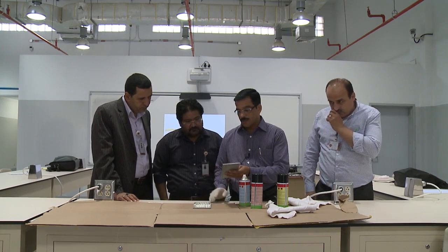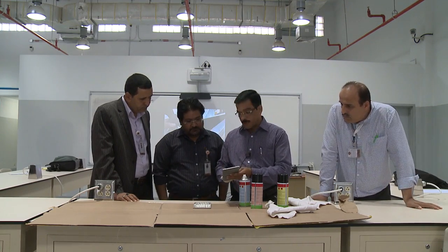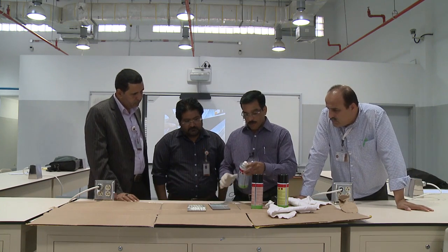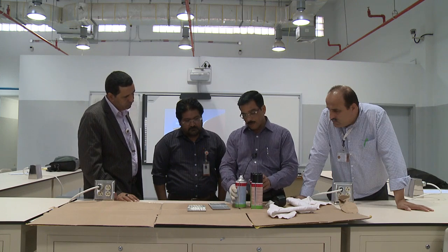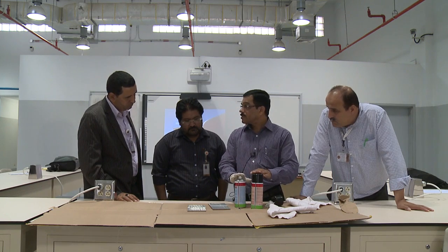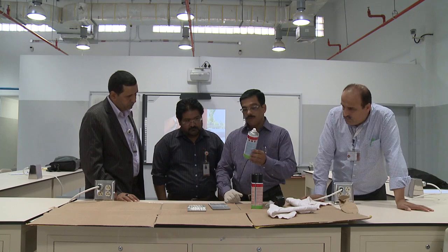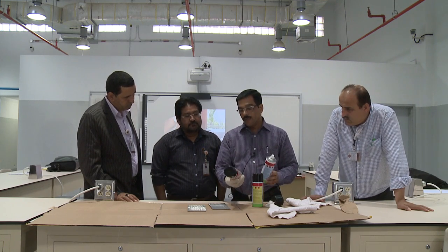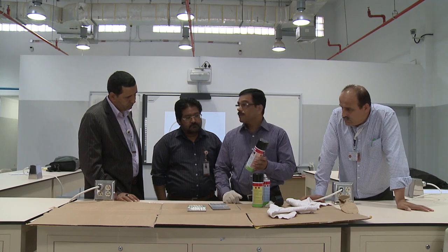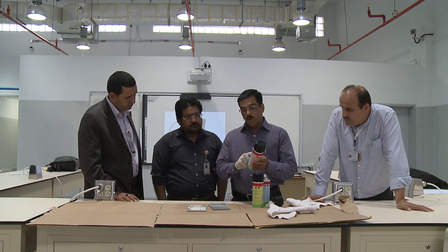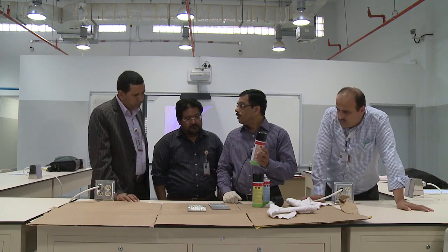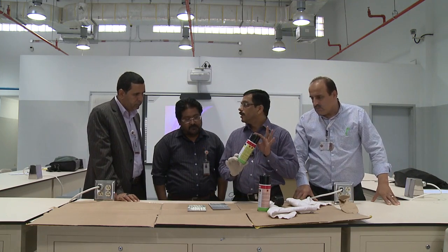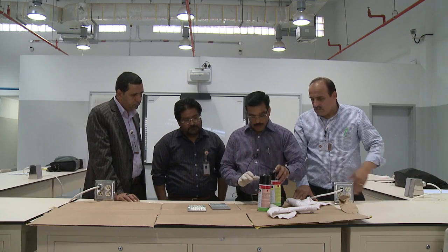The same as we have some artificial defects. Test pieces are there. This is low carbon steel. So as we told, our procedure for PT testing, minimum we need 3 chemicals. One we are using for pre-cleaning, it's a cleaner, and another one is the penetrant. So we are using solvent removable visible penetrant, and the other chemical is the developer. So now let us start the procedure.